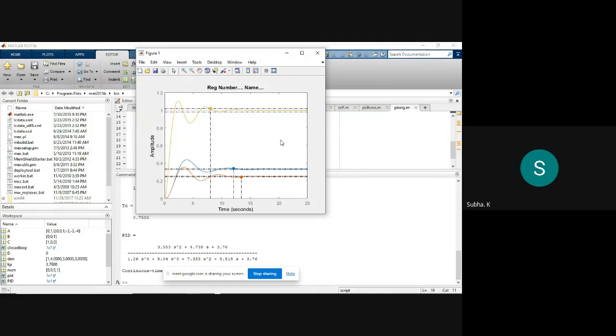You people understood or not? Yes, ma'am. So here the settling time happens very early. Earlier it was 34.5. Now it is settling at 8.01. So you fix it up like this only. You will be designing the PID controller using Ziegler-Nichols tuning.